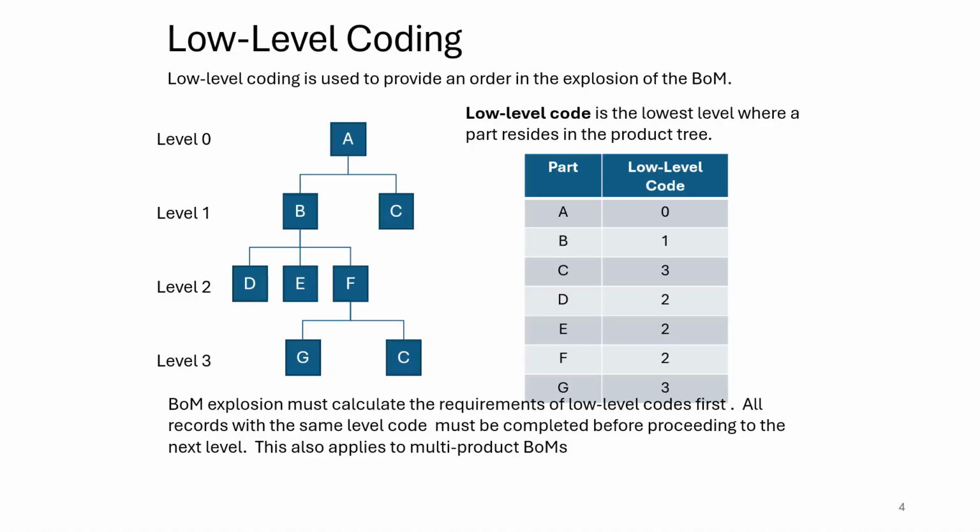So when it comes to drafting the MRP, it's a top-down approach. Coming back to this BOM over here on the left, first we calculate what is the MRP for the entire assembly A. So let's say we need 5 units of assembly A. To manufacture 5 units of assembly A, we might require 10 units of subassembly B and 20 units of part C. So only if we know how many units of assembly A we will need will we know how many units of subassembly B and how many units of part C we will need.